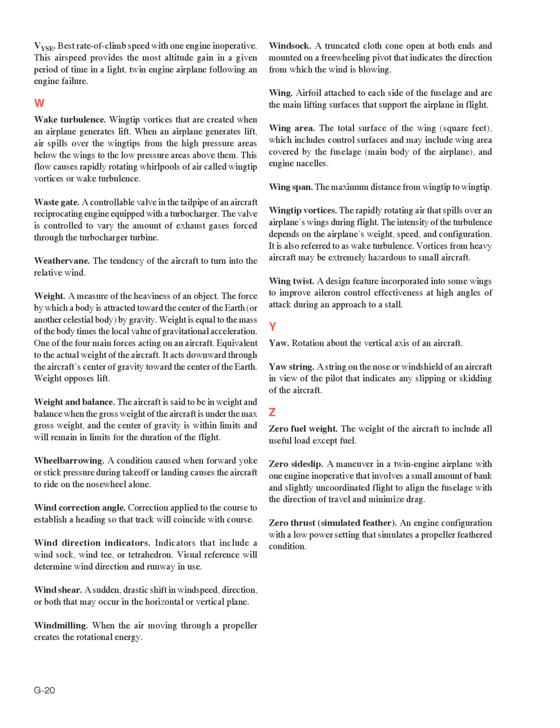VYSE. Best rate of climb speed with one engine inoperative. This airspeed provides the most altitude gain in a given period of time in a light, twin-engine airplane following an engine failure.